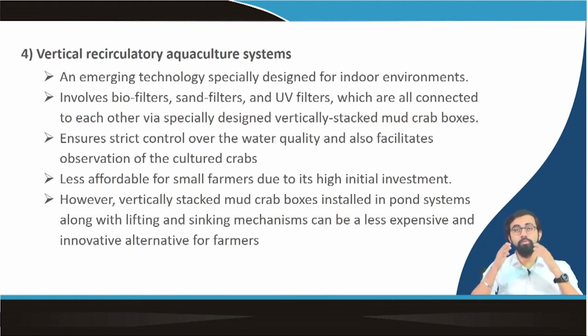If you talk about the sand filters, in general we can put them before. So, for what purpose are sand filters used? They get rid of the suspended solids present in your plant. Because it is brackish water, it generally has very high turbidity. So, these sand filters reduce the suspended solid level of this kind of water system.